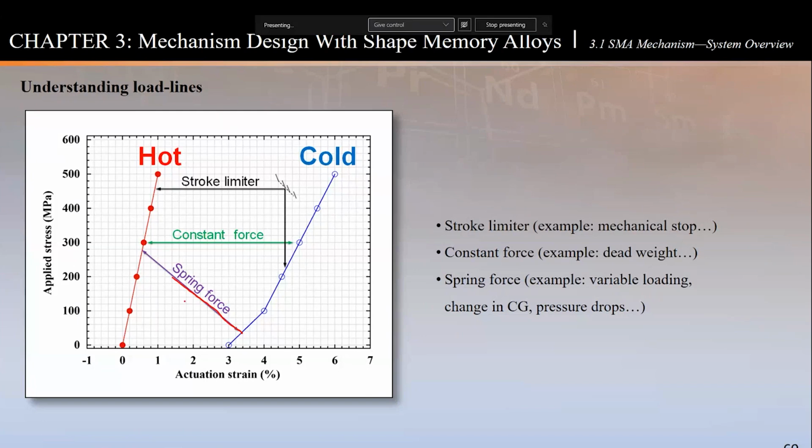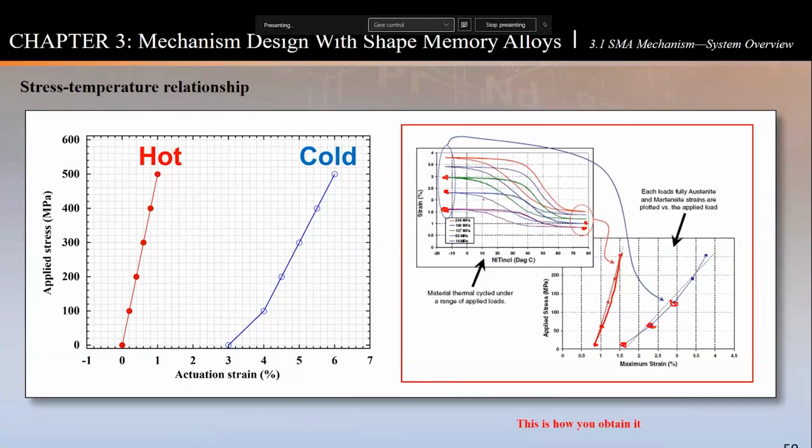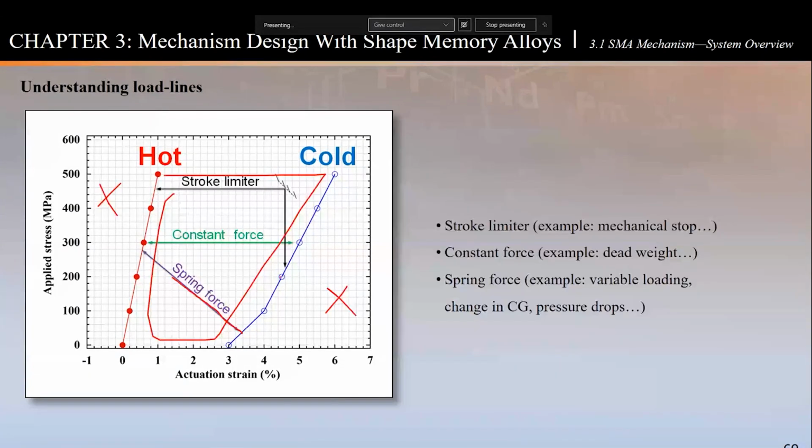So there could be a combination or any other sort of form, and I have seen some crazy different load lines that go in there. But realize what I did: anything that I do is in this box, right? Nothing is out here, outside of my range. If you don't do your characterization, spend a few minutes or hours doing this test, collect this data, and create this relationship, it gives me my box, and I can play in this box all day long. This is what I live for with my actuator, and I can create any fancy load line I want. All right, so that's very important in the world of shape memory alloys.